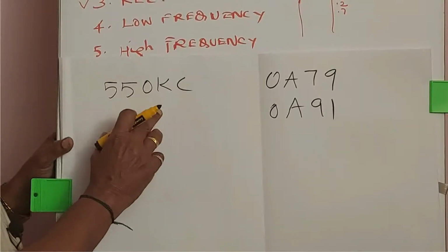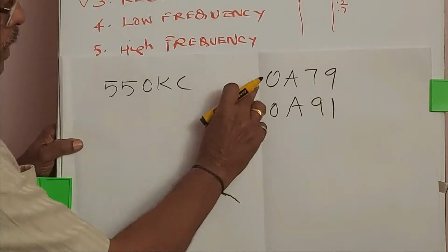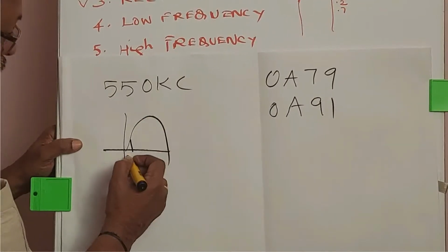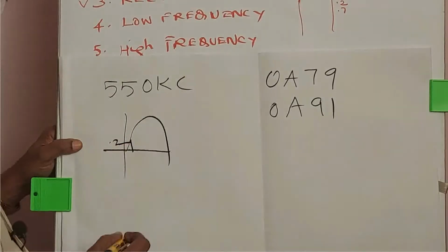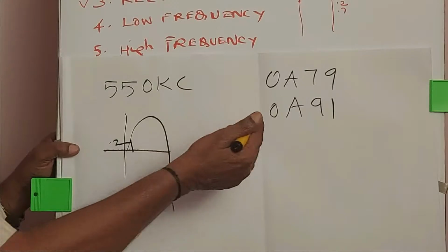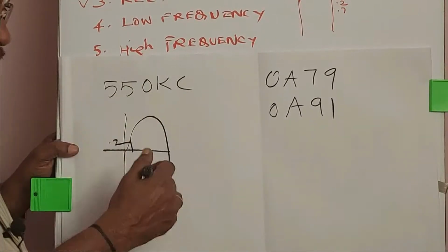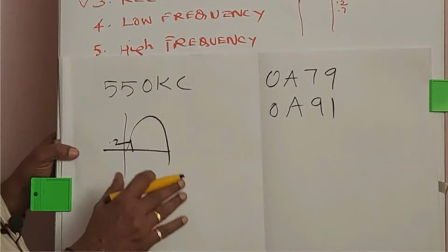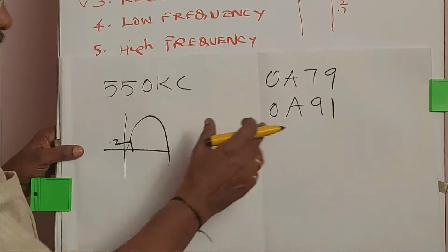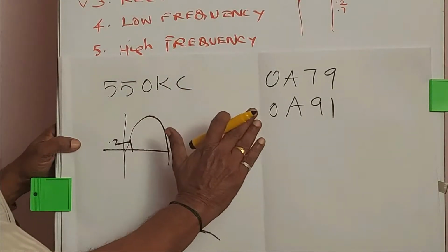Frequency above 550 kHz. Normally, for example, in AM demodulator circuits, they are made of germanium because they have to rectify starting from 0.2 volts. If you use a silicon diode, it will rectify only from 0.7. Here, there may be certain information between 0.2 and 0.7. Therefore, only germanium has to be used. Like that, these diodes are useful for high frequency rectification only, high frequency rectification in communication equipment.